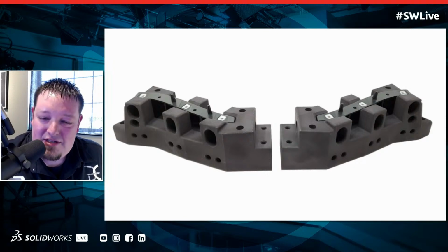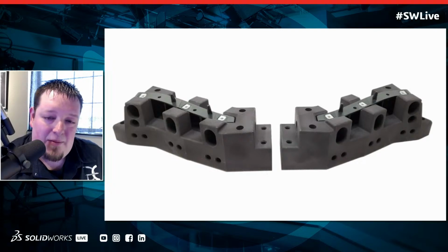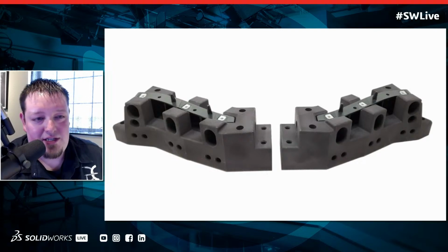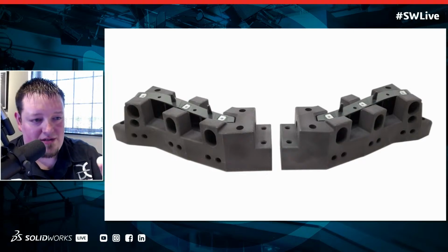So what we have is these kind of slots that you see here. We actually have proximity sensors that go through those slots, and those detect the metal clips. So if the operator forgets to put a clip in one of these stations and they hit cycle finish, the machine will go, I see all the clips, or, oh, wait, this clip is missing.